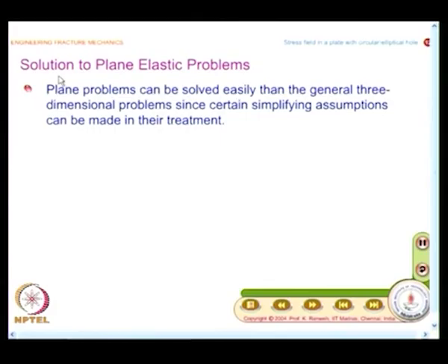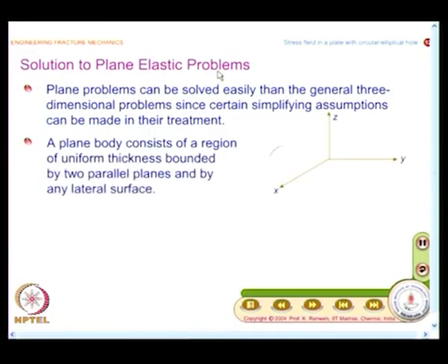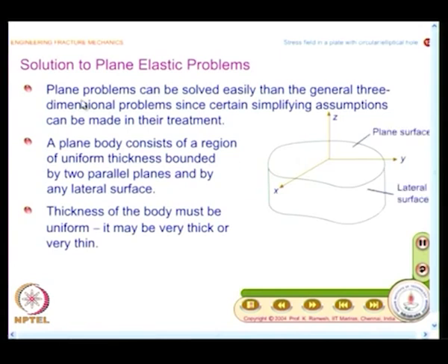But what we would do is, we would look at solution to plane elastic problems. In fact, in this slide just observe the animation, you do not have to try to draw this, we would spend time on each of these special cases separately. At that time, if you draw the animation, fine. Plane problems can be solved easily than the general 3-dimensional problems, since certain simplifying assumptions can be made in the treatment. That makes your life lot more simpler. In fact, a variety of practical problems could be simplified either as a plane stress or a plane strain situation.